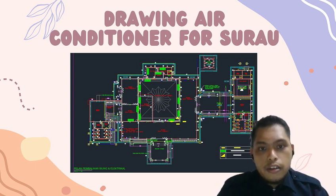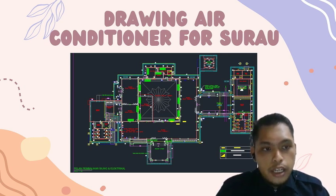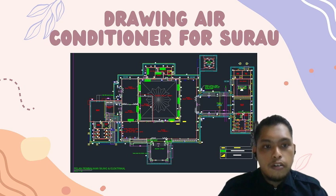This air conditioner also has a three-phase system, same as the lamp and socket, and it needs to be balanced. And for the air conditioner, it is required two air conditioners for one circuit or one phase only. Thank you.